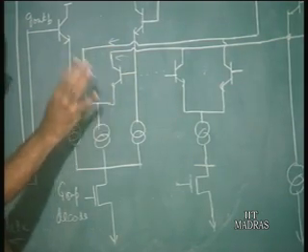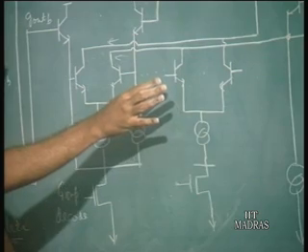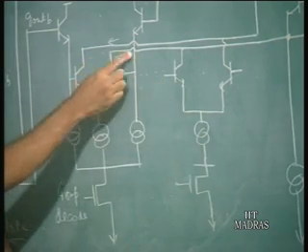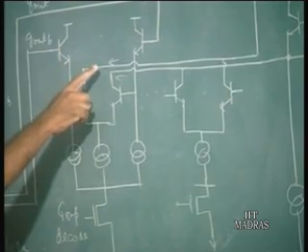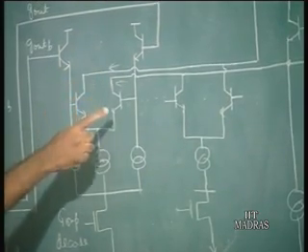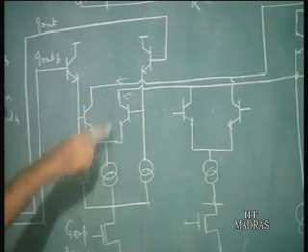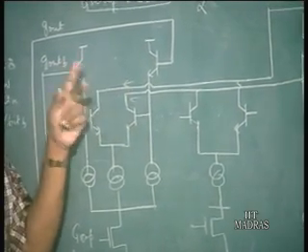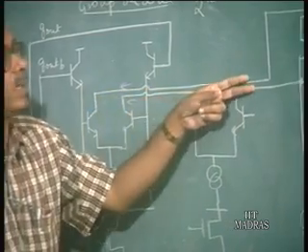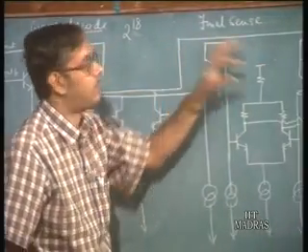So, basically you select one out of the 2 to the power 11 groups. The current flowing, the difference, is actually corresponding to one of the 2 to the power 11 groups, and in that group one column, and in that column one particular cell. So, we basically have the information corresponding to the particular cell we have chosen available on this pair of lines. Now, let us come to this part which is the final sense.